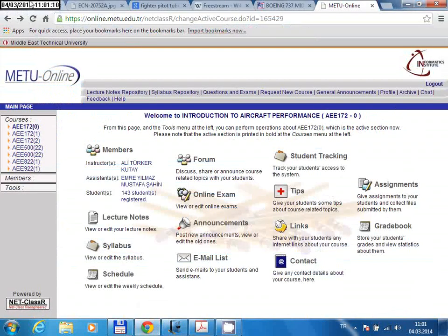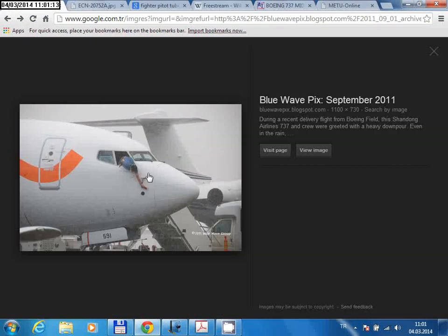Let me show you some pictures here. So here you see some pitot-static tubes, and the pilot, or the co-pilot, is taking the mask off. I think this is before the flight. So you have to make sure that these tubes, which are very tiny, are always clean and free of water or ice. So these are really very sensitive devices, and you have to really take care of them. Modern pitot-static systems have heaters to prevent ice accumulation. But even then, some small insects can go in there, and that can cause an entire aircraft to crash.